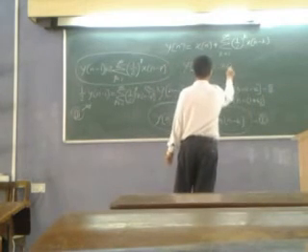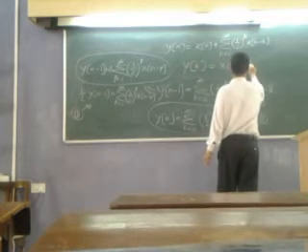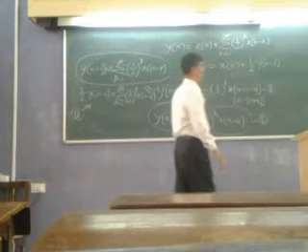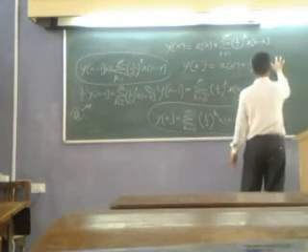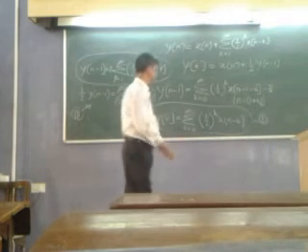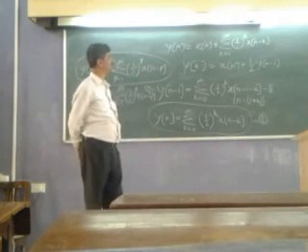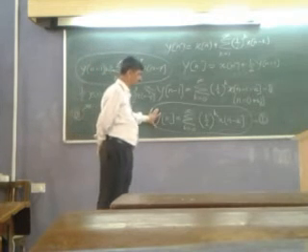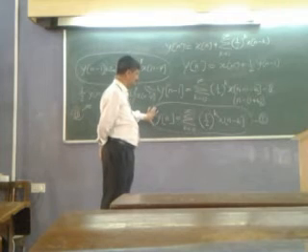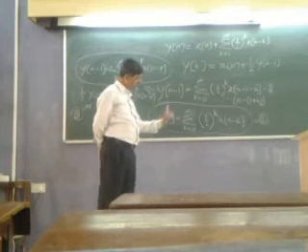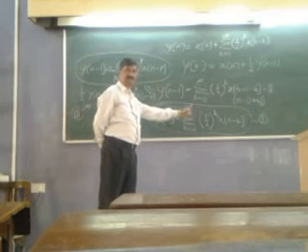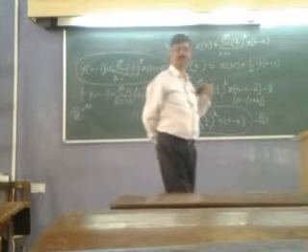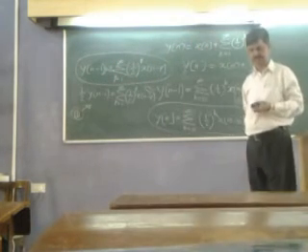So I can come to this solution: yn is equal to xn plus half yn minus 1. So this convolution expression, which requires the output to be a combination of previous inputs in a particular manner, is rephrased into a difference equation. The convolution equation is rephrased into a difference equation.